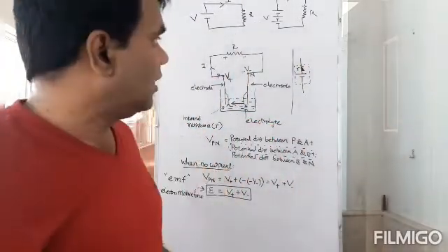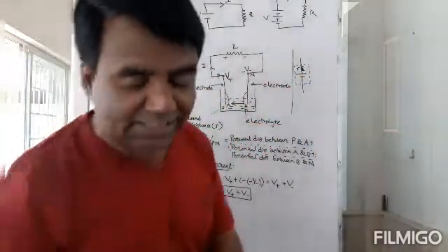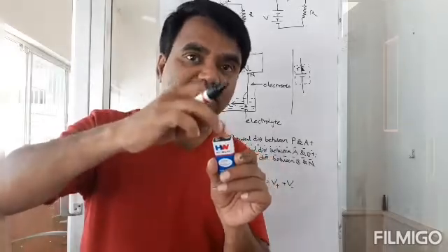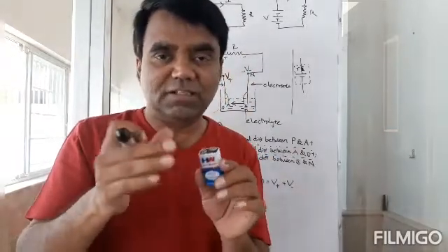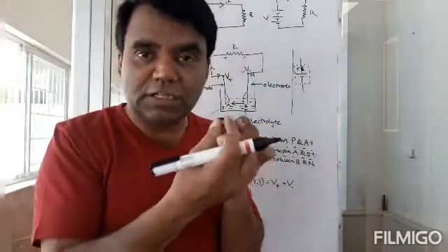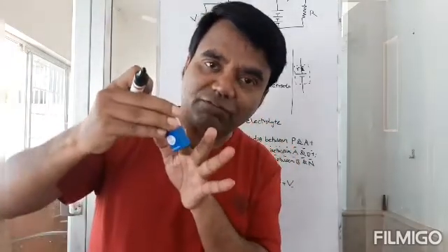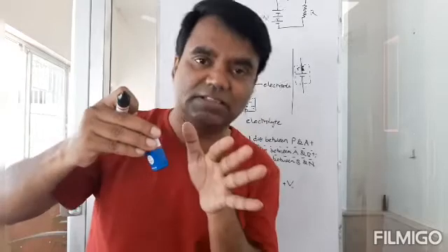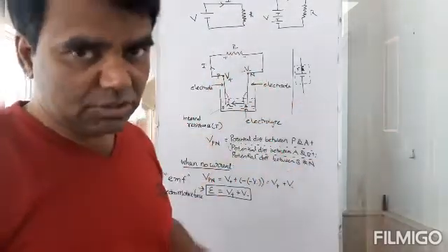I cannot bypass this at all because I can connect the resistor only here. I cannot put it inside, right? So I can never bypass the resistor. It won't work that way. So I can connect the resistor only across the two terminals of a battery. The battery will have an internal resistance and also will have an EMF, as we just saw.